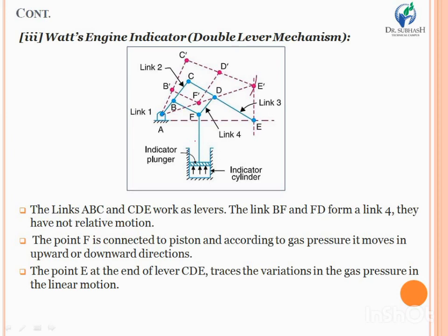At the end of the lever CDE, there is a link which connects the common point F to the piston. And if you give it any motion in any direction, either clockwise or anti-clockwise, at the end you are getting the reciprocating motion of the piston inside the cylinder.